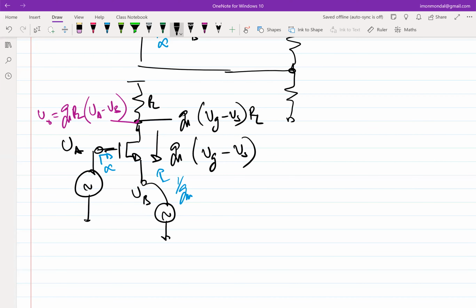If that is the case, we cannot use this as a difference amplifier because we don't have an ideal voltage source. If we had an ideal voltage source instead of VB, then I could have as well stuck that voltage source directly at the source without having any issue, right? But since you never have an ideal voltage source, the moment you connect anything to the source, it is going to draw current, and that voltage source is going to have its own internal resistance. You are going to have a drop. So the source will not see exactly VB, right? Source will see a reduced value of VB. So the transistor will load the source, in other words.